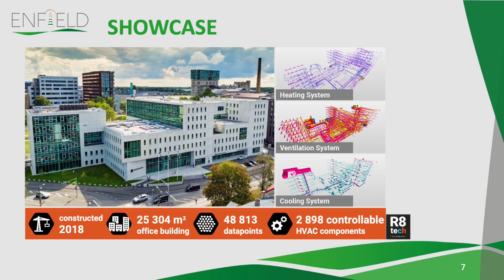So approximately 50,000 points, and almost 3,000 points are controllable. Controllable means that we can change these settings. We can increase, decrease airflows a little bit, change some temperatures, valves, etc. So each controllable component is responsible for the energy consumption, as we saw from an example about intelligent control system. So we have to control each point in a smart way.